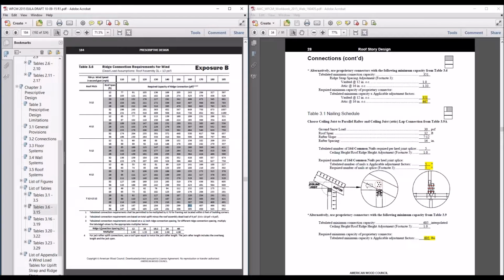Again, the footnotes down here, footnote 3 in this particular case, shows that our default is 12 inches on center. And so at 16 inches on center, we'd bump that up by 1/3. So back in your workbook, you see where that 1/3 factor is coming from, and so you see what the loads end up being on that structure or on that particular connecting device as well.